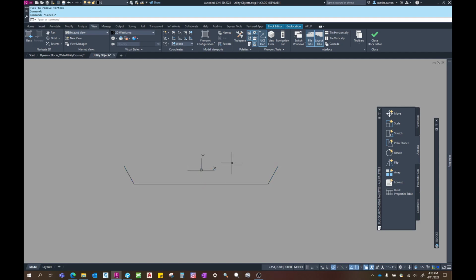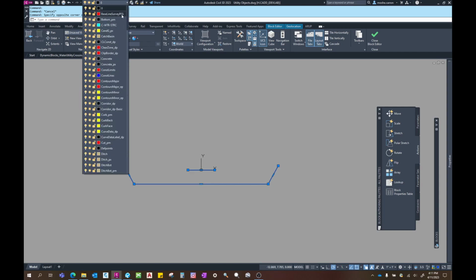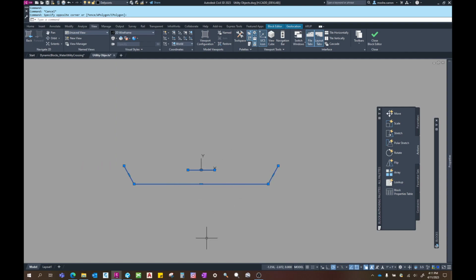Next, with our lines now set up, let's make sure that they do not show. So I'll select the two, go to my layers, press def points, because last thing I want is for them to show. So now I have these both on def points.